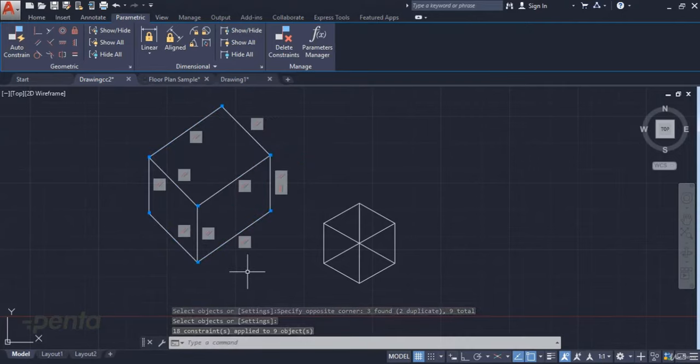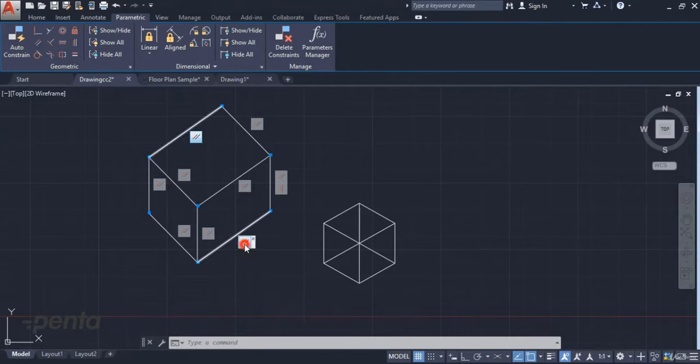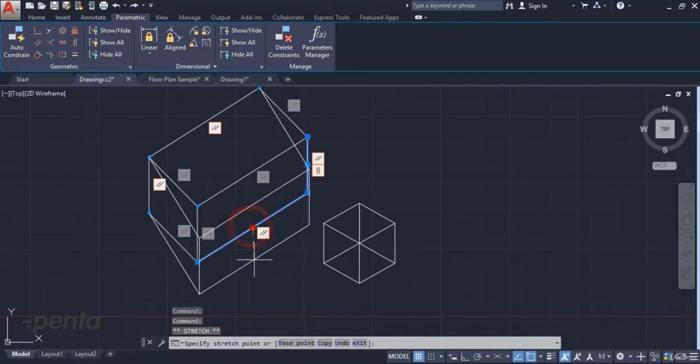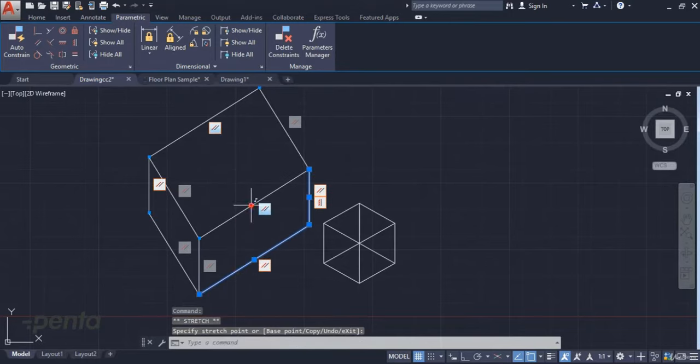most logical way. Here, we have two parallel parts. It assigned them as parallels. When we look here, it assigned these two parts as parallels. There are also parts assigned end to end. You can see that it assigned them automatically. Here, when we move any part, when we stretch them or move them, all the other parts will be moved with each other. As you can see here, it's much easier and logical to work on the parts now.